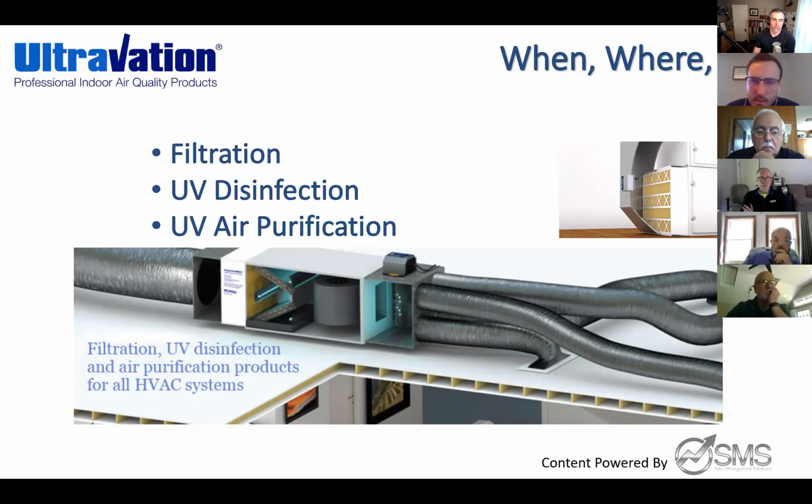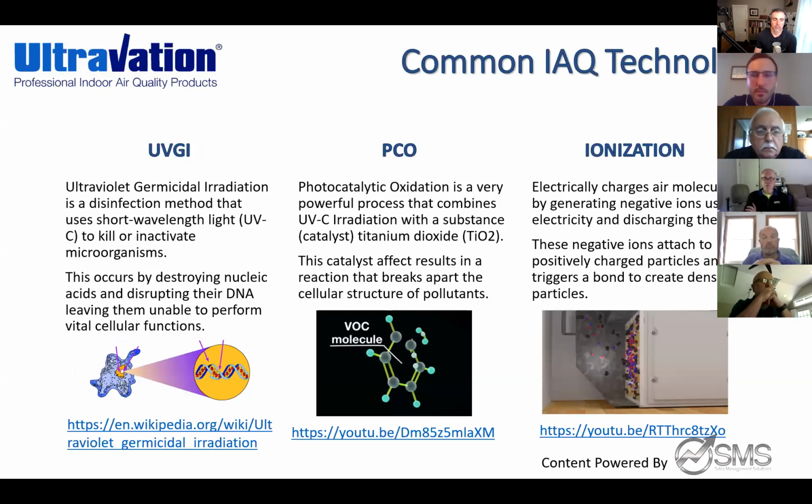So next we are going to look at the UV lights over the coils there. There are 2 different ways you can treat. You can treat for in-air disinfection and surface level disinfection. You do want to treat for surface level disinfection by putting UVC lamps over the coils. And then if you look in the airstream, after the blower wheel there, we also are treating in the airstream as well. We're going to get into each of these products individually to go a little bit more in depth with those. We'll go ahead and jump to the next slide.